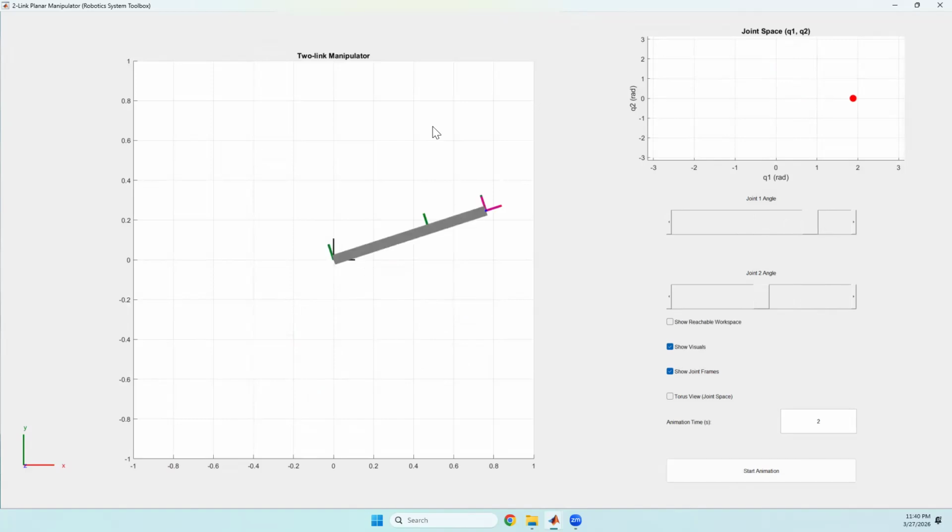All of the points here you see actually come from how the robot is built. We cannot reach anywhere in space, and that makes sense. The robot has some limitations, and this is actually known as the reachable workspace of the robot. And you can compute it, by the way, and you can see, for example, all of these blue dots here I visualize with the reachable workspace. Any point that's marked in this region, the robot's tip, the robot's end effector, can reach.